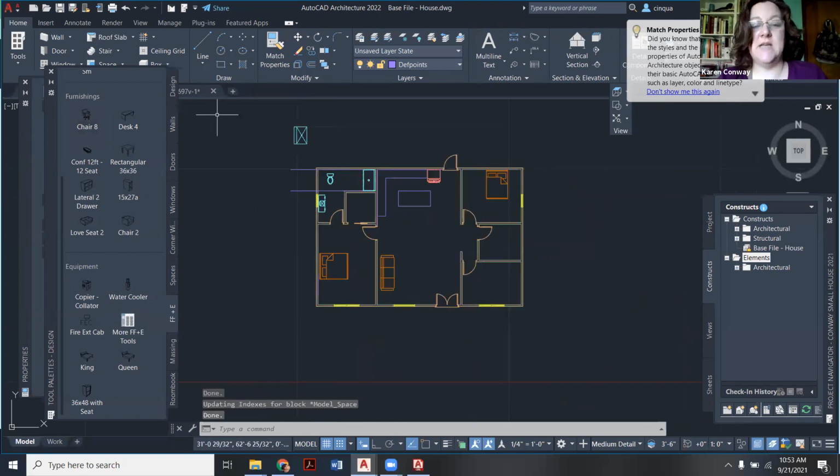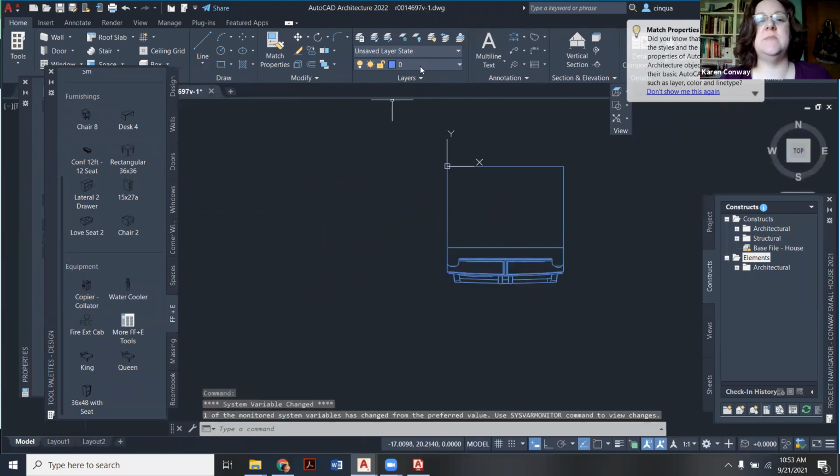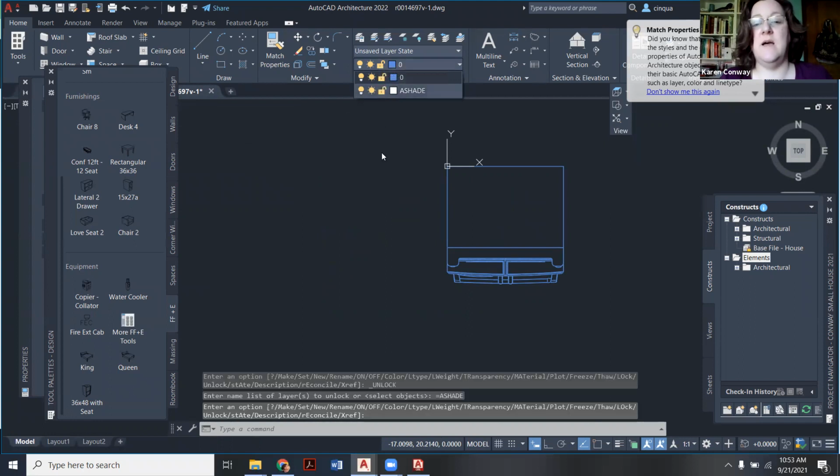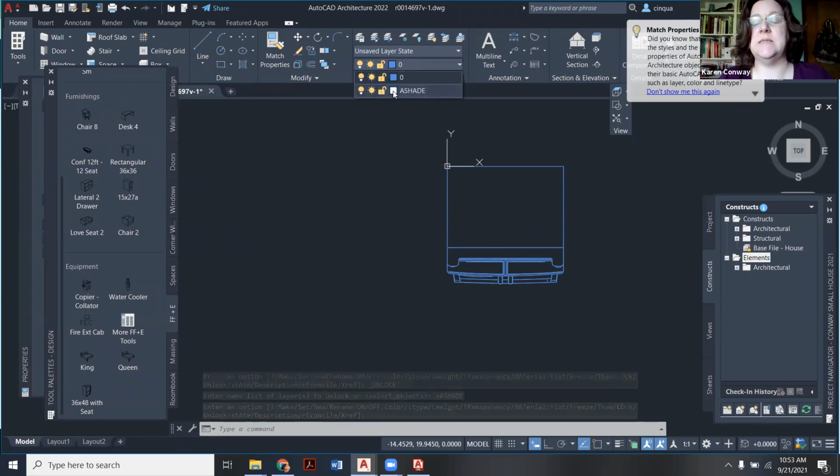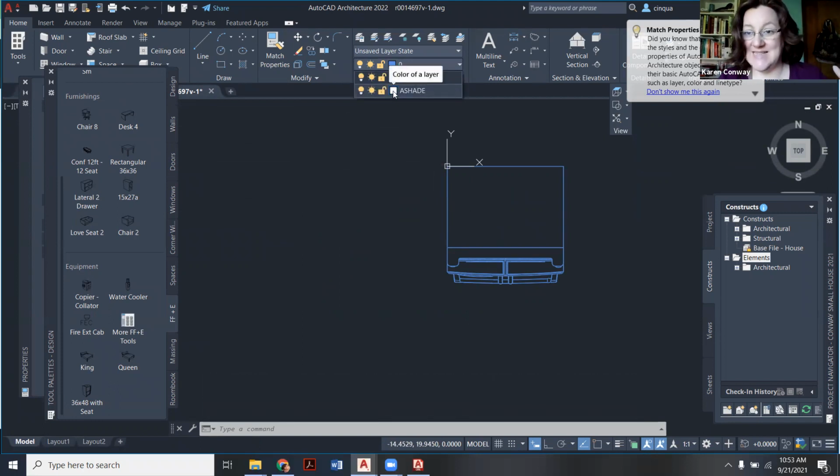All right, so that's how you're going to edit blocks. Some of them you might run into some weird hiccups, and every year I end up helping folks troubleshoot it, and it's not your fault. Sometimes there's a lot of odd programming going on behind the scenes. One thing I'll show here is sometimes if you look up here, see how that says there's a lock on it? Often we have to unlock it to be able to edit any part of the drawings. So some of these appliance ones are drawn on a layer that the person has locked. We have to unlock it first before we can edit it. All right, but remember, I'm going to be doing a lot of troubleshooting and helping you with this in class too.